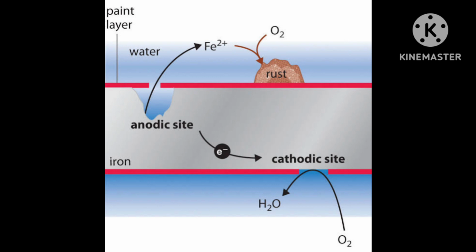A question is asked. I told you that Sn or Zn, stannous or zinc, protect the other metals. An electrochemical method is the third method I am talking about. An electrochemical method is to provide a sacrificial electrode of another metal like magnesium and zinc. Magnesium is also used. That is called a sacrificial electrode.